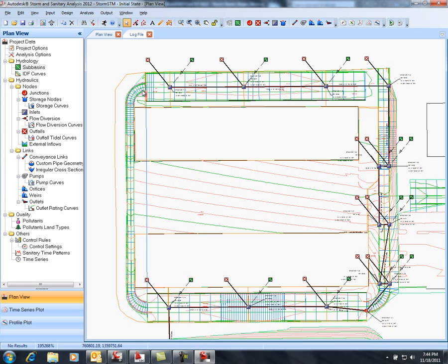So any water that comes across the inlet that doesn't pass into the inlet and instead continues to move on down the gutter towards the next one, we can have what's called a bypass link to determine or calculate and take into consideration that flow with respect to how much is there and exactly where it's going to go. So it's automatically set up for us additional links that we can start to determine or create those bypass situations.